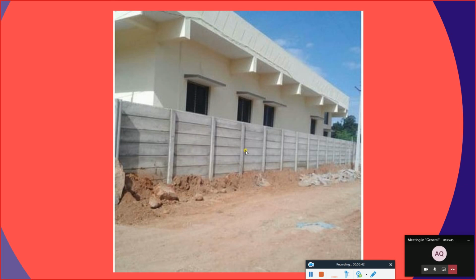Okay. Now, one of the common issues that's normally happening in case of a boundary wall is that when your wall is very lengthy, if it's very long, and in certain areas we have wind loads or areas near the wall, you will see that your boundary wall is falling. We have even had one of our houses where the boundary wall has fallen down, either because of the wind or because the other neighbor has started to excavate. So one of the major solutions for this one is to place columns between certain distances.